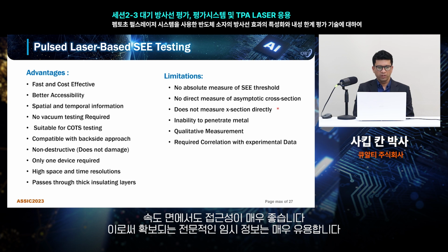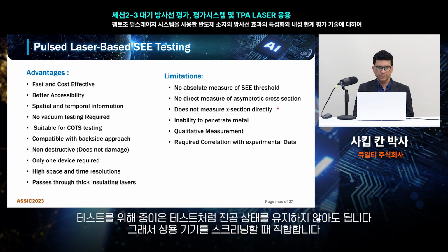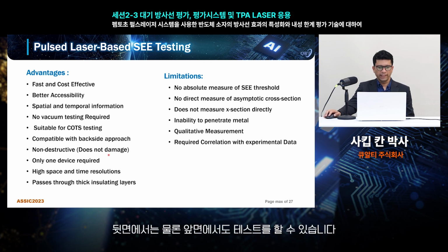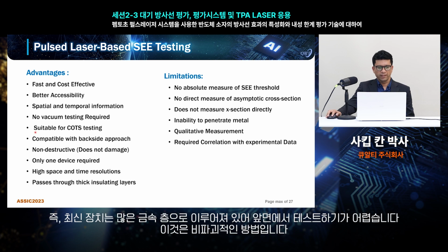The spatial and temporal information it provides is very useful. No vacuum is required for the testing, as it is required for the heavy ion testing. It is suitable for commercial device screening. It is compatible with the backside approach as well as the front side approach. I mean, in modern devices, it is very hard to test from the front side because of the metal layers, the large number of overlayers.